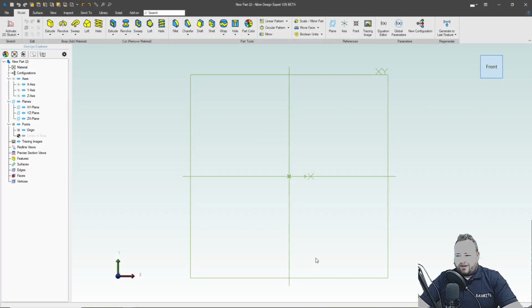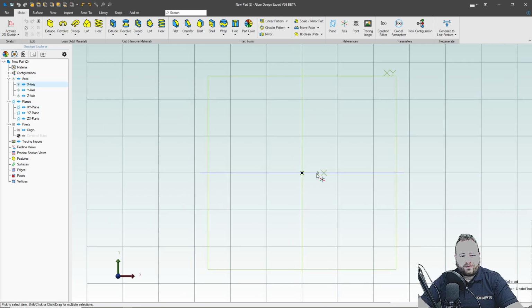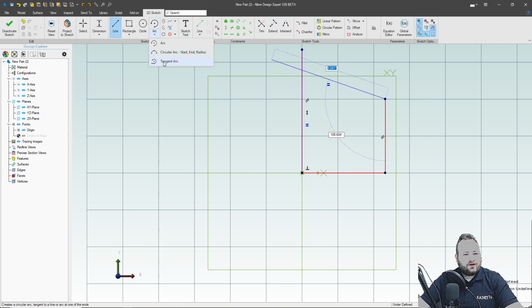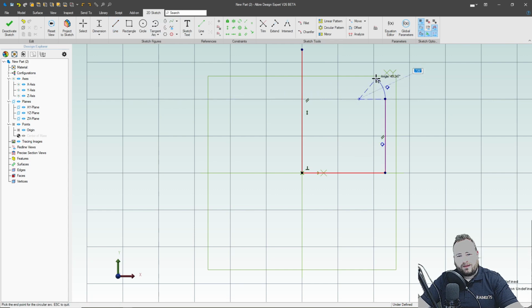All right, so we'll get started with creating a sketch. Let's do so in the XY plane. I've got no reservations about putting my origin right here at the bottom corner, right? So I have like my big vertical, big horizontal, and then we'll sketch out kind of a bottle shape with tangent arcs here. So go tangent arc, tangent arc, tangent arc.